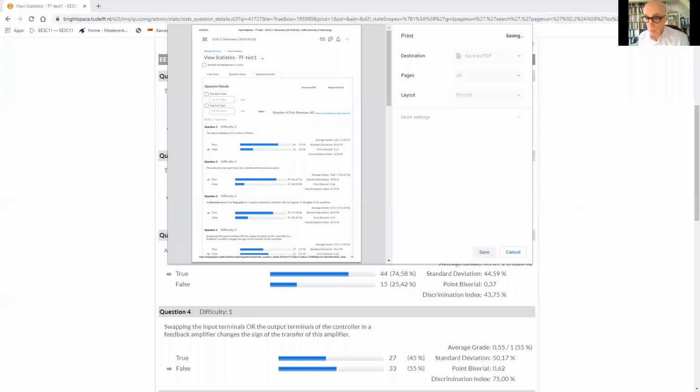It's just during the modeling, you made a model and two things cancel. That's all. So then you add the coefficients so that you always end up with coefficients for your uncorrelated noise sources. And then you calculate the spectra from the spectra of these uncorrelated noise sources and the squared coefficients that you have.